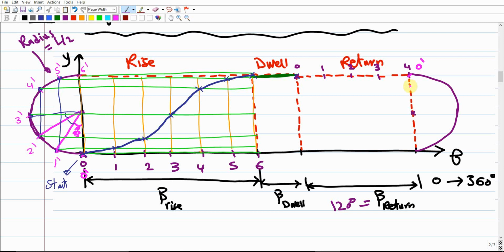So if you measure 45 degrees, then you're going to end up with a mark. So this is going to be the second mark, 1 dash, while this angle should be 45 degrees because we divided it into 4. The third mark, you can do the same technique: draw a vertical line from this mark. If you draw a vertical line, you're going to end up with the mark that should be here at 45 degrees. Then your objective is just to mark here like 3 dash. This is going to be the 4 dash.